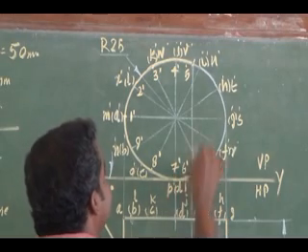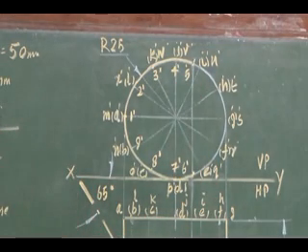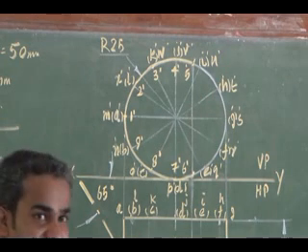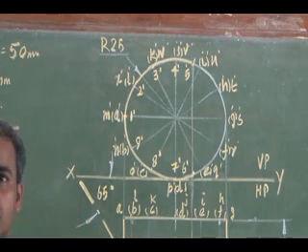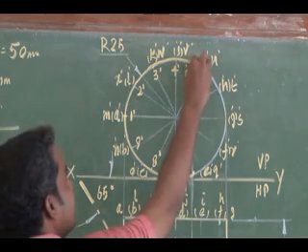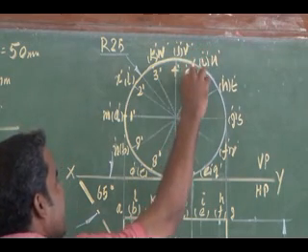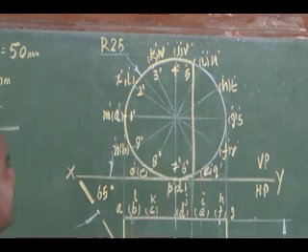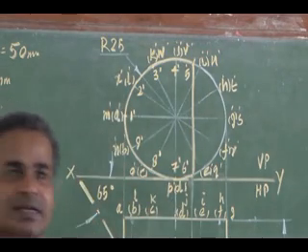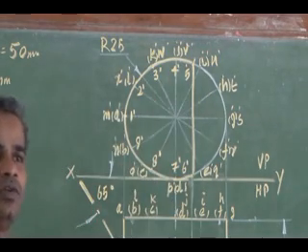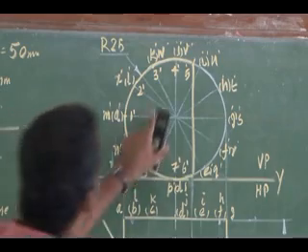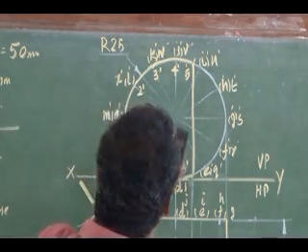How do I have to connect the cutting points 5 and 6? It cuts the base here. It cuts the base. Right. So it will be connected as a straight line. 5 to 6 will be connected as a straight line. So this is going to be my apparent section in my front view. So you can catch this apparent section in the front view.